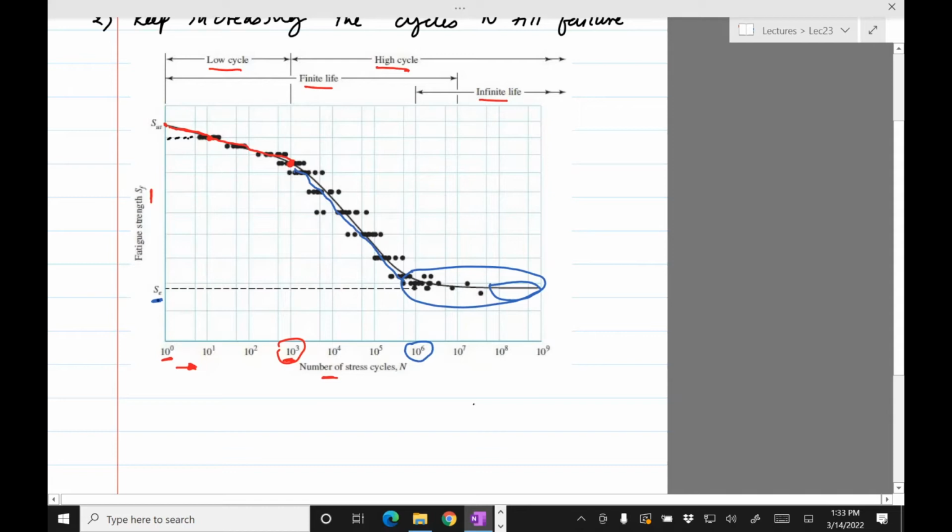So something like this has implications for any machine element which is subject to fluctuating loads, right? When they say that an aircraft is going to fly for X number of years, they'll say that it's for so many cycles. So you can predict the number of cycles depending on how many hours it flies. And so you can have benchmarks or recommendations on when you want to replace parts based on just this curve, provided it's for that material for which you're designing.